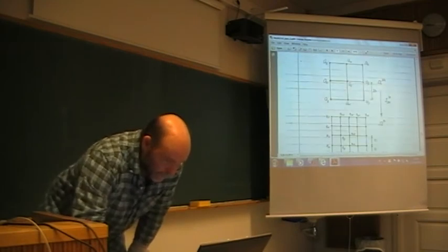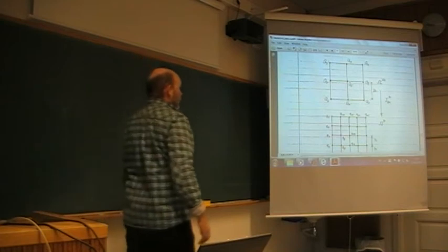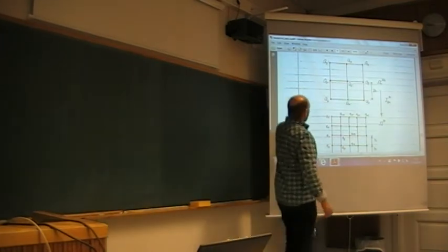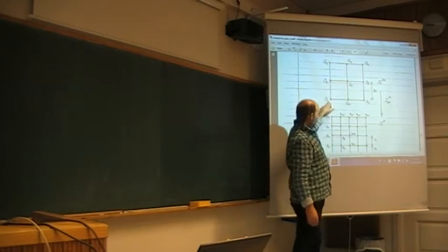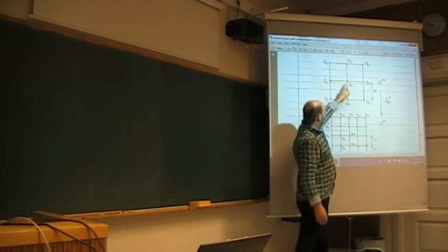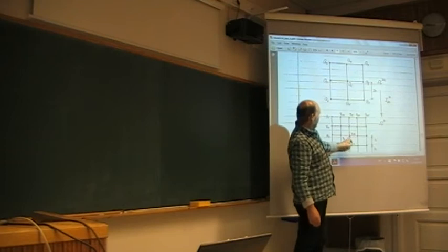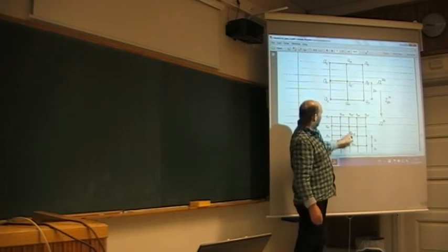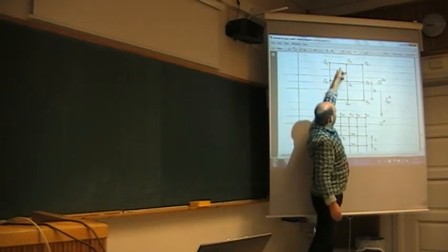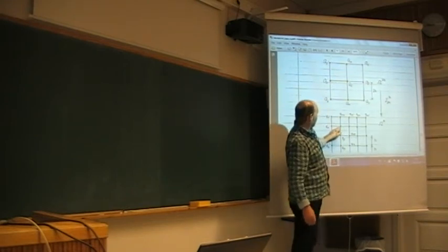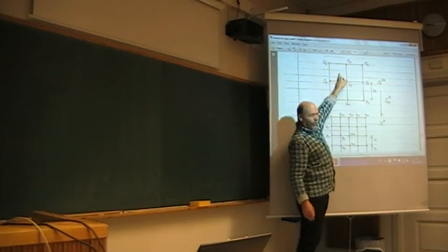So this is your coarse mesh. You have all your unknowns in the corners. Of course, the corner points hit the corner points directly, no problem. But then in between here, this one, well, that's an average between these two. But the center point here, that's an average of 4.